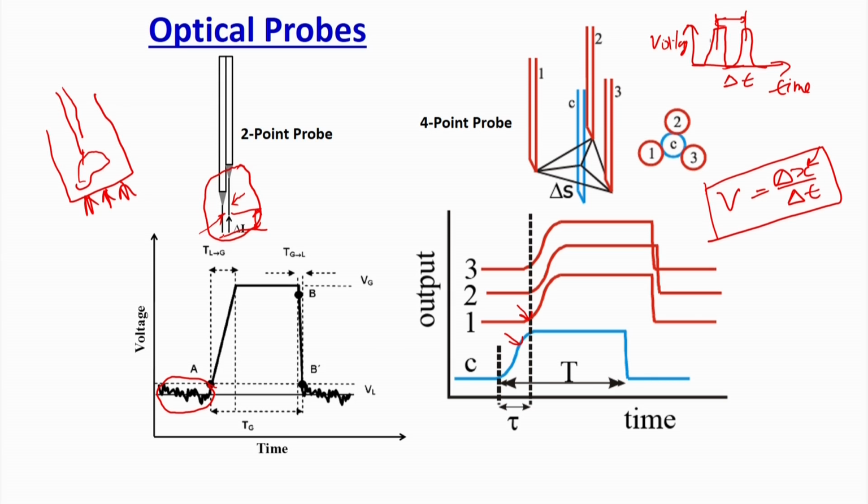Now, the 4-point probe is also important not only to measure all the 3-dimensional velocity, but also, suppose I have inserted the probe in this way and a bubble is passing through this line. Then there is a possibility that it will not touch the second probe, and in that case you will miss the signal, you will not have the data at that point. So, several such combinations are possible. To avoid that, we design a 4-port system.